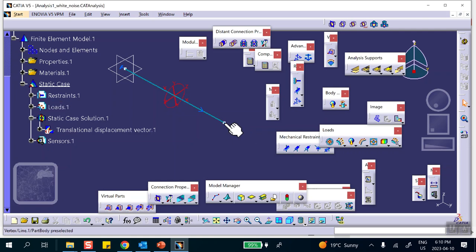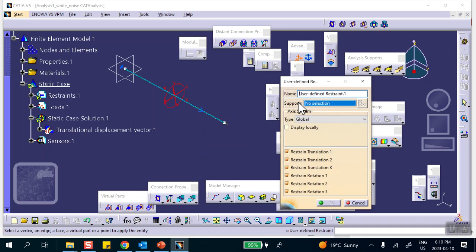The reason I want to do this is that I want to take away all those extra degrees of freedom which cause this thing to bend, and rotate, and things like that. So I'm going to apply user-defined right there. And on that point, I'm going to say just move in the direction y.